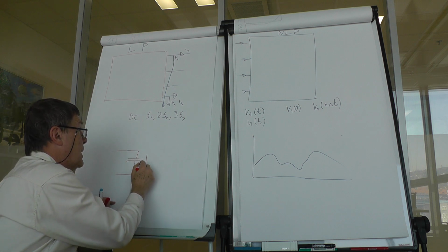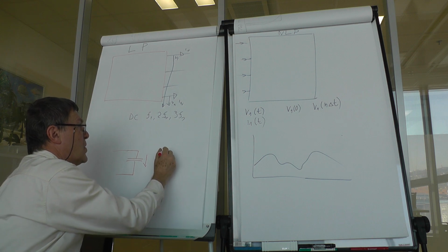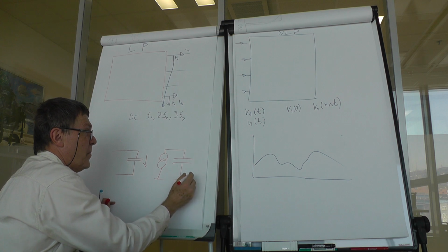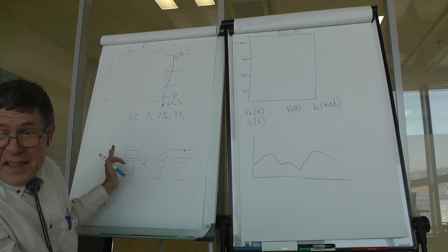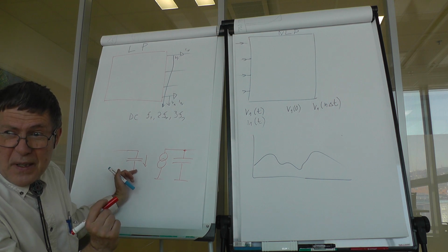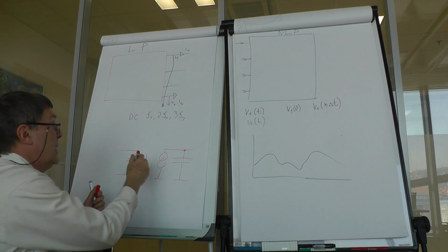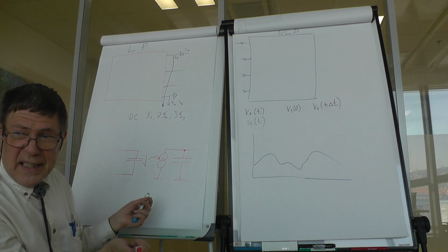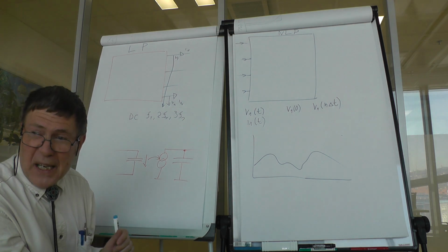Then you have the voltage over it driving a current source, and you have the drain capacitance. Now for small signals, this is a nice linear model. Once you increase the signal, both the transconductance would be nonlinear and those capacities begin to behave nonlinearly.